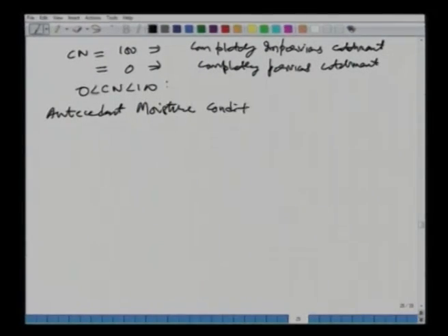Before I actually go to that, I must mention that this curve number has been defined, or calibrated, and given by the Soil Conservation Service depending upon the soil type and the land use pattern. The SCS has classified all kinds of soils into 4 kinds, class A, class B, class C and class D. Depending upon whether you have clay soil or sandy soil or loam or whatever, you first find out whether it classifies into A or B or C or D.